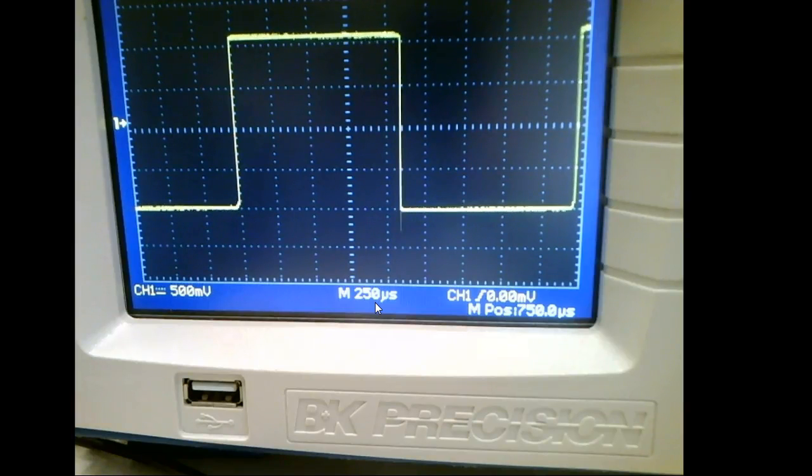You got it? Okay? Yeah, y'all have to get, scopes and test equipment do not use engineer notation. You probably noticed that on your meter. Like in DC, if you got a 2,000 count meter, when you get up to 199 ohms, it jumps to K. And then you'll see 0.25 K, right? So test equipment does not use engineer notation because they're limited in the number of ranges.